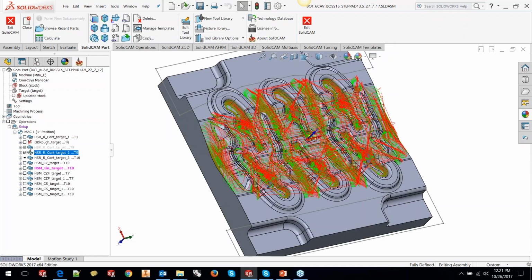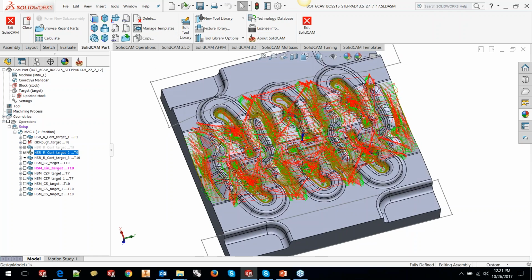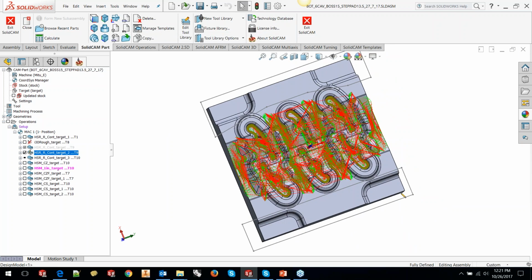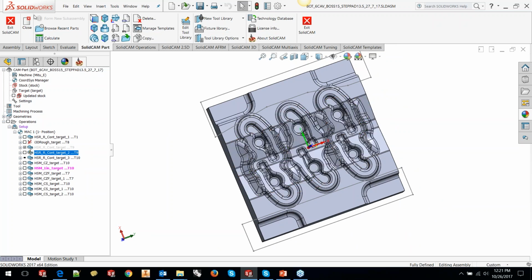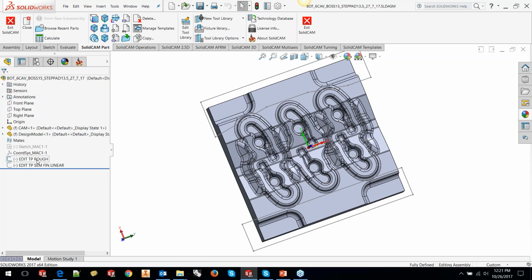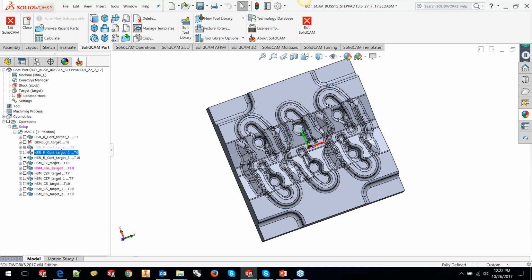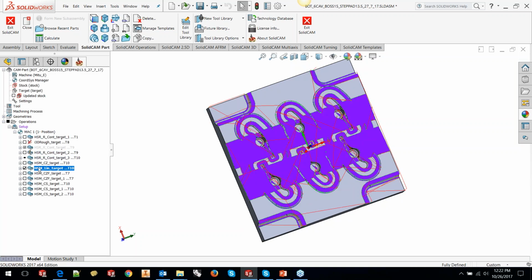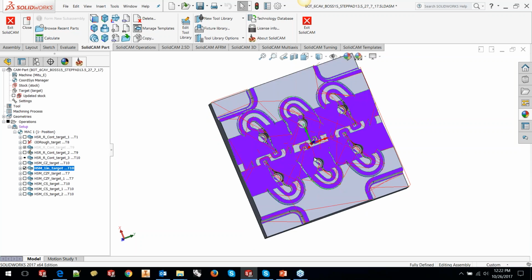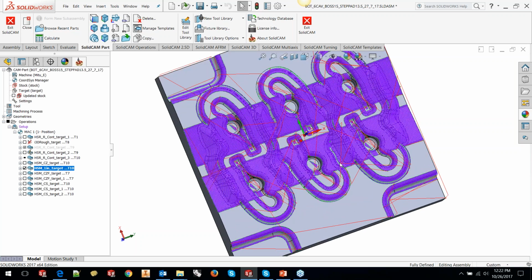So those areas are gone. Okay, that could have easily added another couple of minutes to my machining time, and I've removed them. So that is one example, and the next one is a slightly more complex toolpath editing, because this is generally what is seen in finishing. The slope angle itself has a limitation.